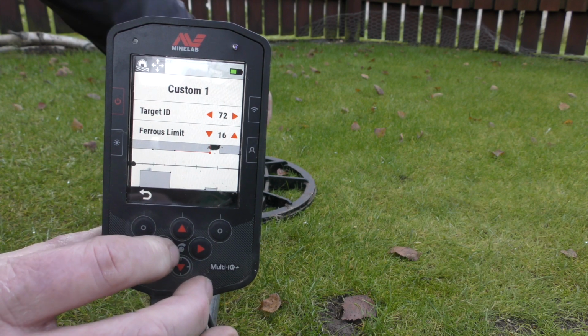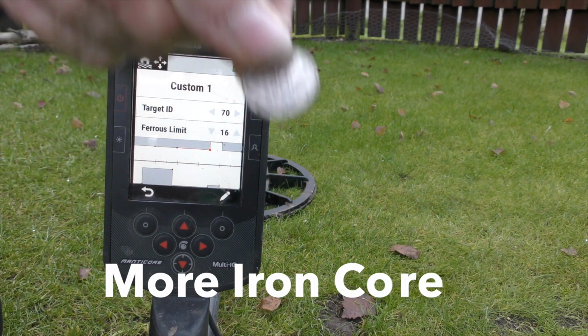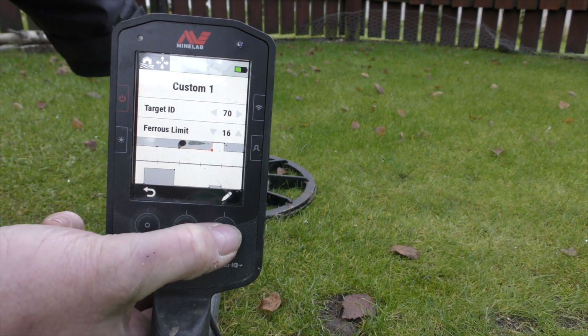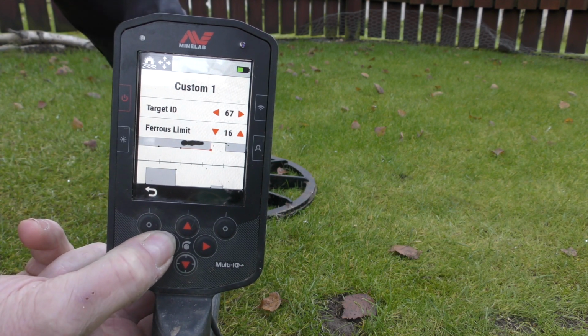Press the arrow keys to navigate to the region nearest to the coin's trace and then press the right soft key to enter the edit mode. Wave the coil over the coin at a range of heights, adjusting the ferrous limits until all of the target trace is captured inside the white area.